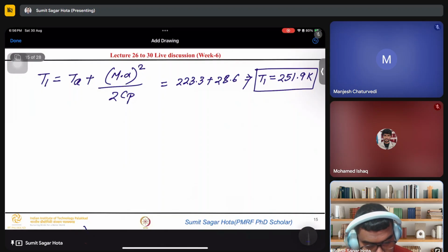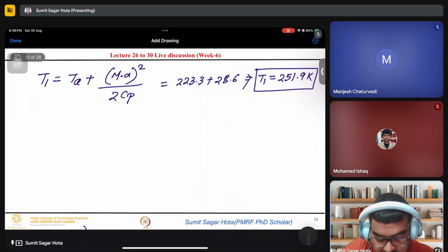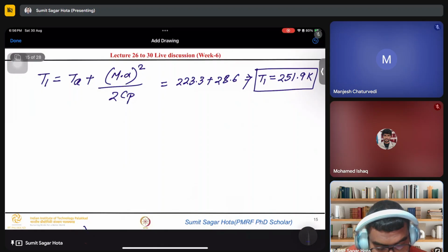So now for this, we cannot actually apply the simple relation, because it's actually a subsonic flow, but especially in these kinds of conditions where Mach number and all these parameters are given, especially for turbojet engines, we cannot directly apply the simple pressure ratio, or assume it as an isentropic flow.